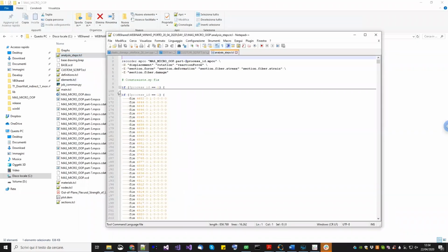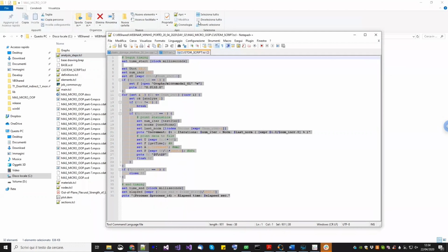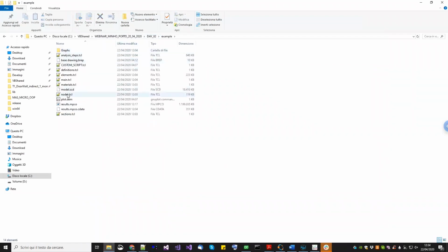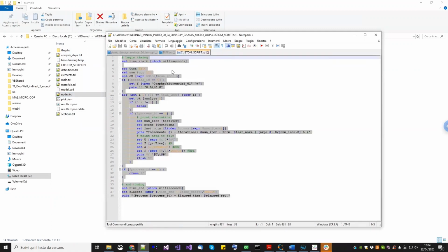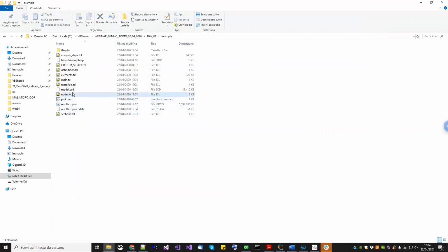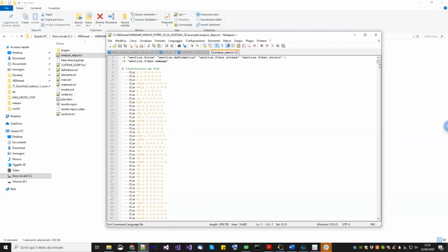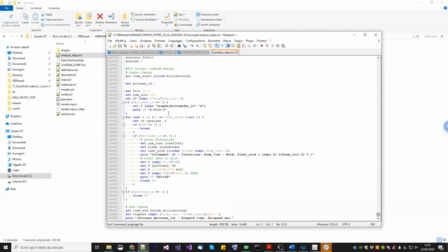from, let me see, where is the solver here? Actually, it is not this one. It is the one that we are working on now, which is this one. As you can see now, everything is not partitioned. Instead, everything is built on a single processor. And if you want to use this one in parallel, you can simply run the analysis with OpenSeesSP just by specifying the number of processors and changing the solver, where we use the UMFPACK to the MUMPS, like in this place here.